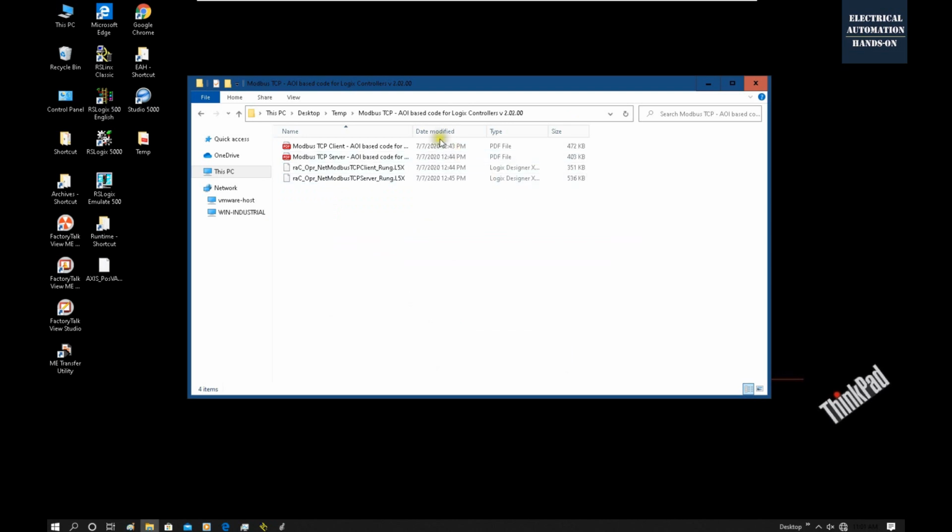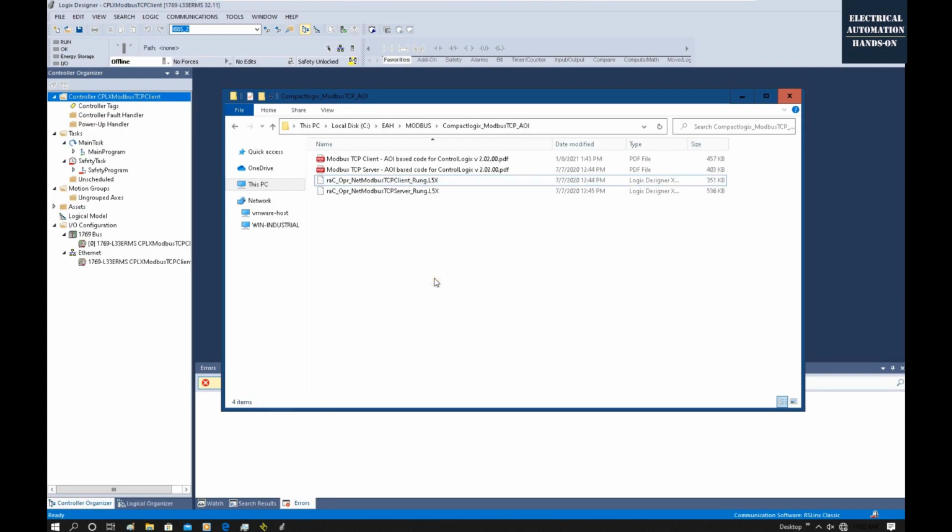And in the meantime, you need to prepare the AOI file we downloaded. In this test, we will use this Modbus TCP Client routine, and you can follow the menus, and my task will basically follow this menu also.